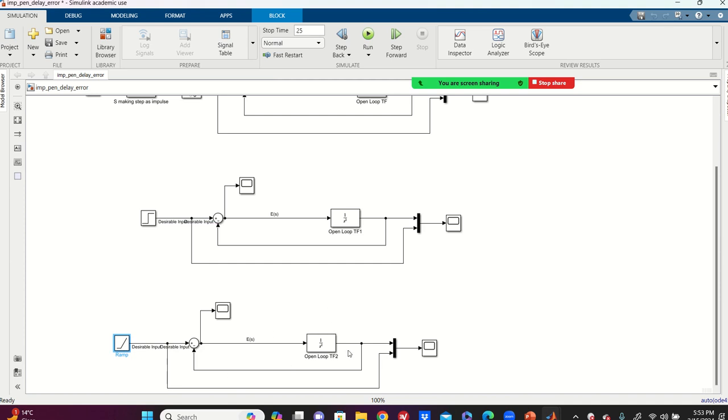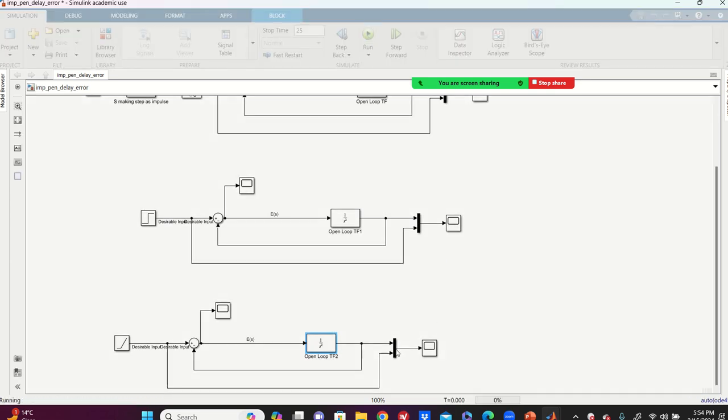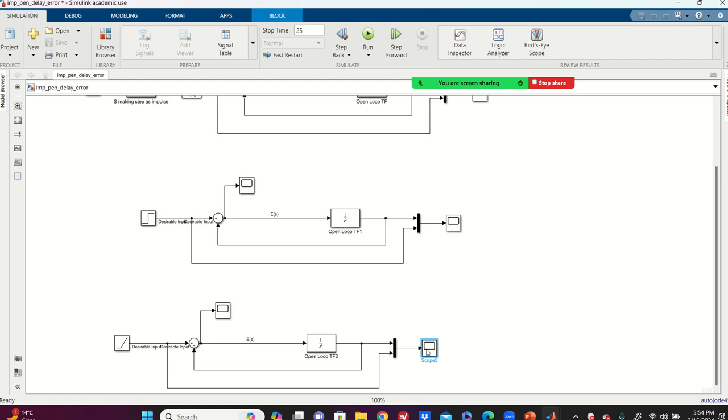And this is open loop G, open loop transfer function. Okay, 1 over s squared. Again, I'm emphasizing a million times: in the feedback control, never put the closed loop transfer function. You have to put open loop G. So if I run this, as your friend said, because the system didn't change, you see that.